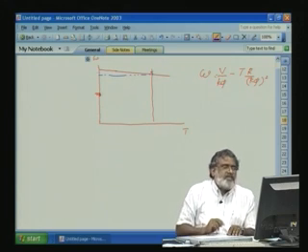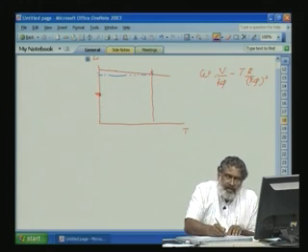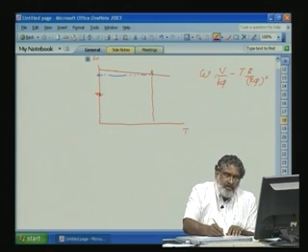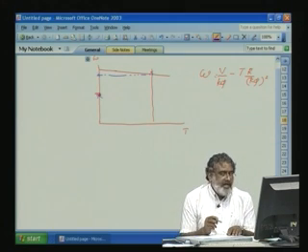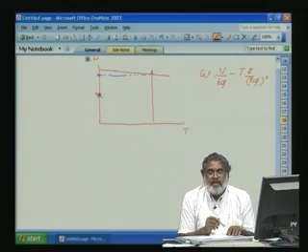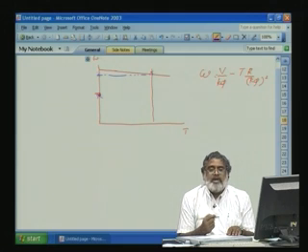Now, this is our present speed. Okay. Now, I want to go from this to this speed. So, system is running. What we have to do? We have to make the current supply to the machine 0. Using our controlled converters, we will slowly reduce the firing angle such that quickly current will come to 0.